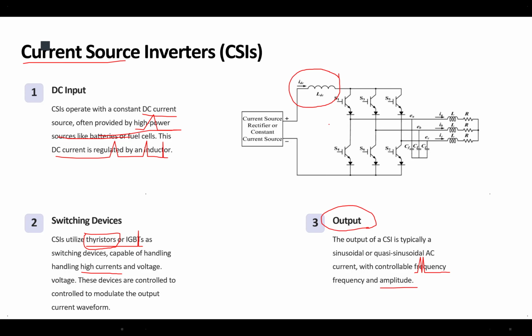They use thyristors. Now, if you have a thyristor, in order to apply the PWM, it's not just a simple input signal to the gate. A thyristor could be turned on, but for turning off, you need to force it off. For igniting, you can use your simple PWM signal as you did before.